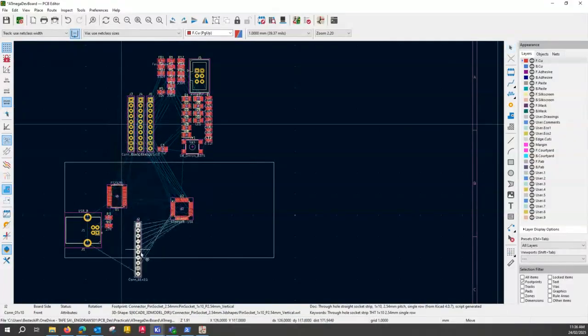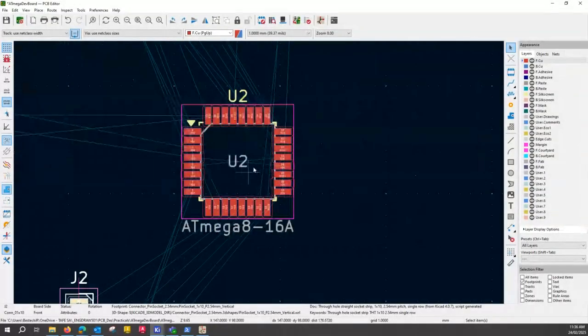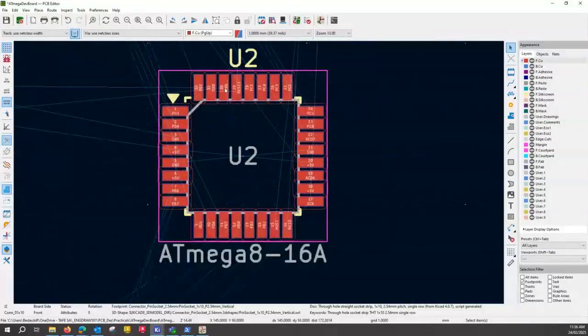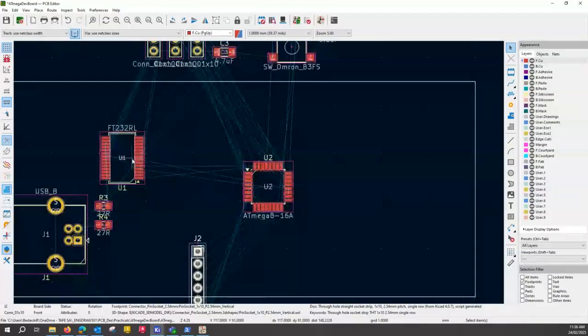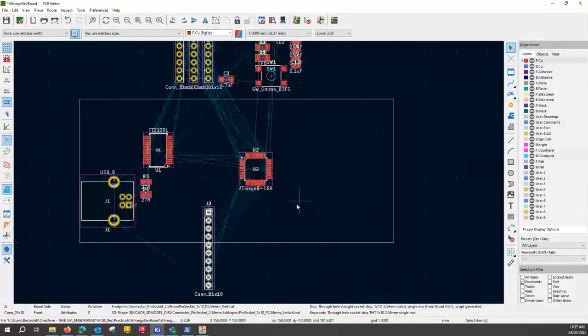With pin headers, let's have a look at our micro, if this is the right orientation. We've got our TX line here and RX line here, which is on the top. It sort of works. You want to keep the flow, and you want to keep this as short as possible. So I would say, yeah, we'll keep it this way. I won't be rotating my microprocessor.